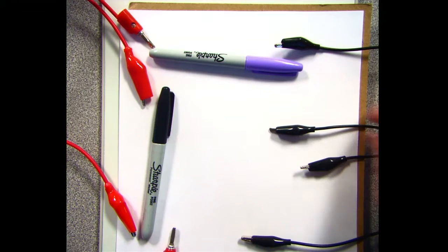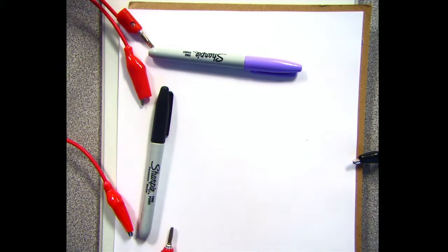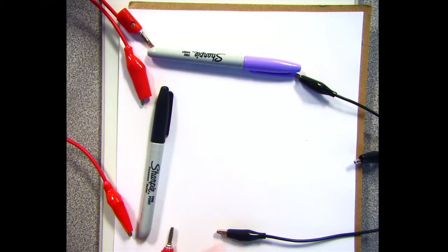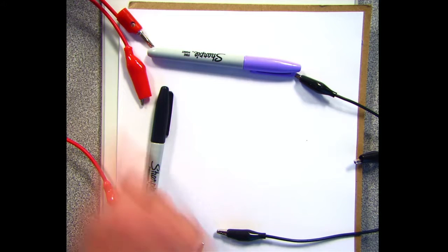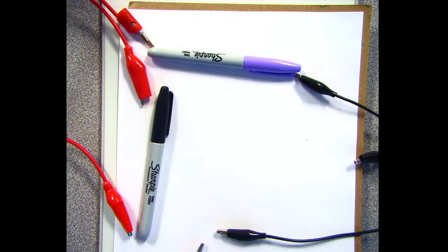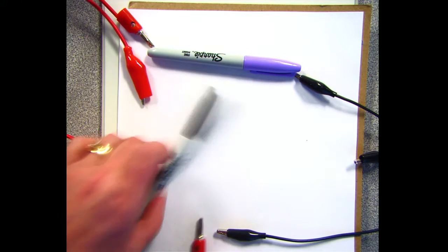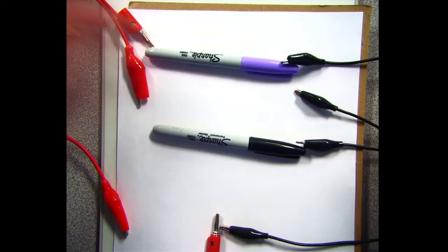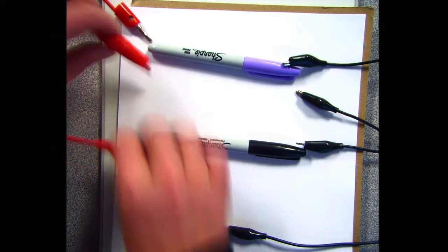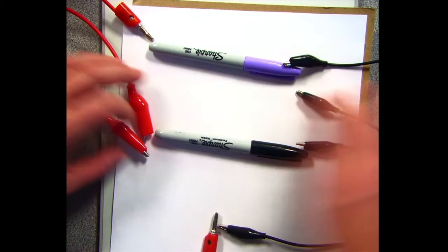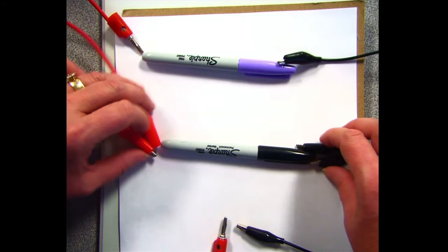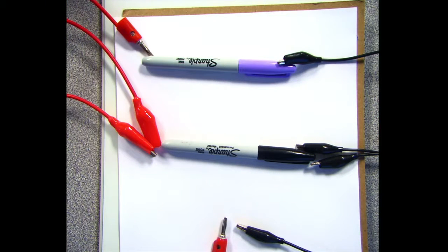So think about the path that your charge is going to follow. When it's like this, I'm going to set up like a ladder, essentially is what I'm doing. I'm going to set this up like a ladder, and my banana clips get attached this way, and that's in parallel. And when I have my things fall through, that becomes in series. So when you start looking at the lab and you're setting up your devices in parallel and series, you're creating a picture that looks very much like this.